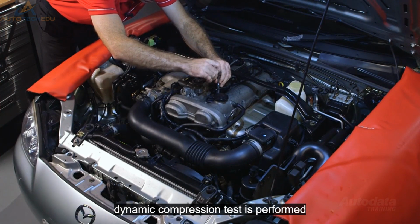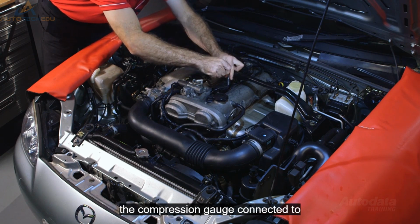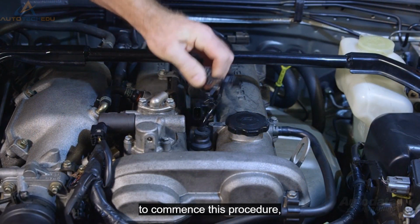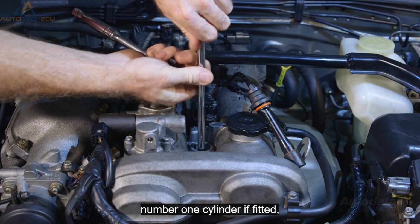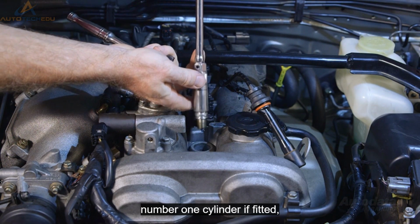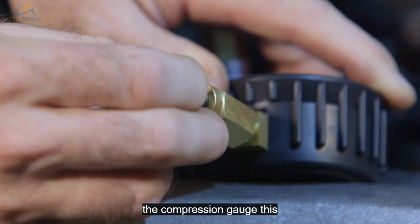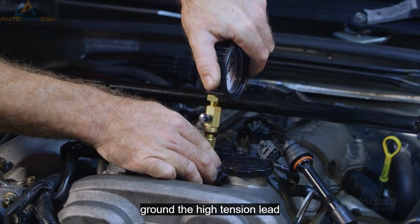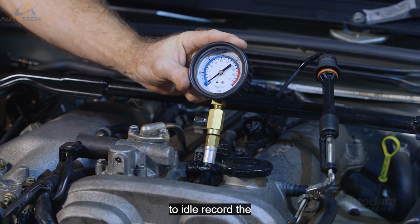A dynamic compression test is performed with the engine running and the compression gauge connected to the cylinder under test. To commence this procedure, remove the spark plug from number 1 cylinder. If fitted, remove the Schrader valve from the compression gauge. This will prevent the reading from being held by the instrument. Ground the high tension lead on the cylinder you are testing. Start the engine and allow it to idle.